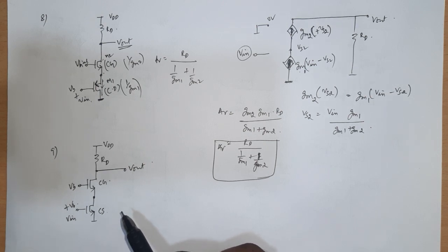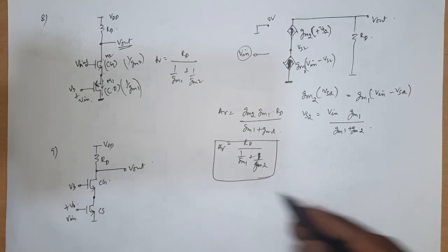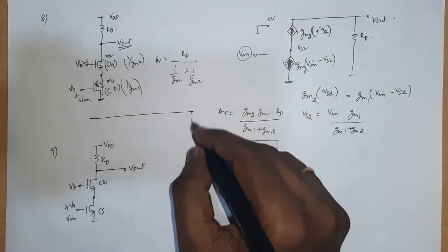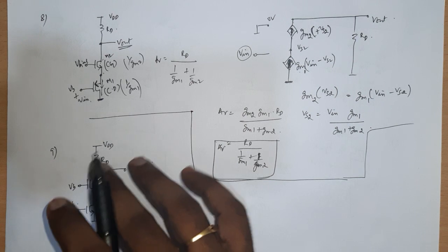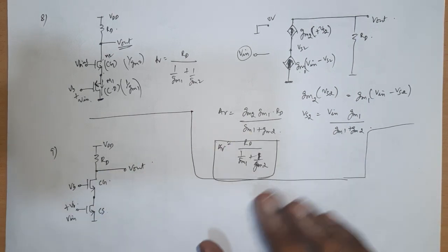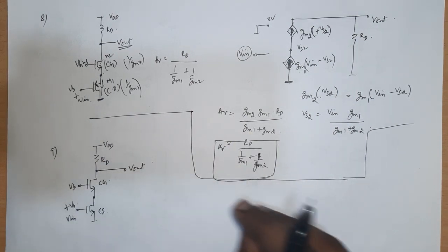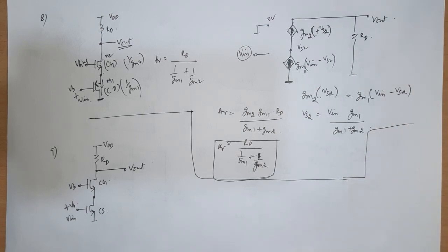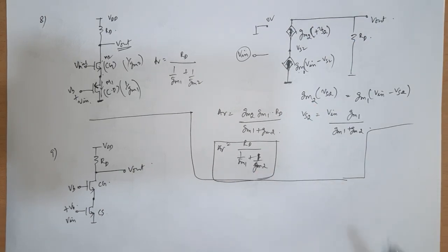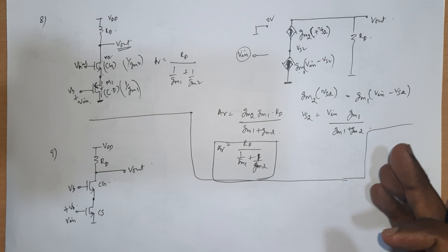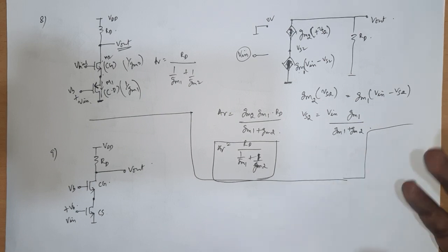Okay, so in this case you will have to work out the problem, because I just wanted to illustrate the fact that you cannot blindly go and apply this technique to all circuits. The technique is possible only when you have the situation that I said, like a common source amplifier with source degeneration or a source follower, or things like that. Then only you can apply the technique whatever we have discussed, right? So once you go through this video again and again and you solve problems on your own and apply those techniques, you will get used to it and you will have your own intuition on circuits.